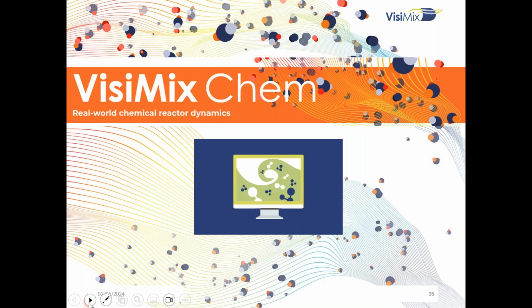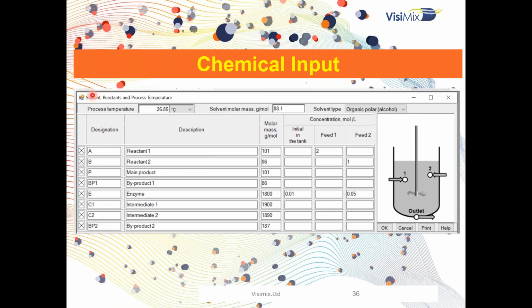How does it work? It works in this way. The first window is to define the materials, the molecular weight, and the concentration in the tank, and the concentration of the feed at the different feeding positions. We have 2 feeding positions and 1 outlet if it is continuous flow. Define the temperature, the molecular weight, and the type of solvent. It can be polar or non-polar, organic or non-organic. We change the way to calculate the molecular diffusivity.